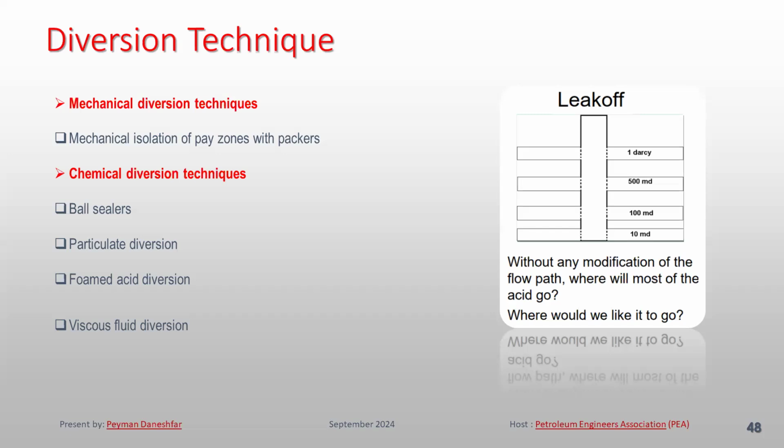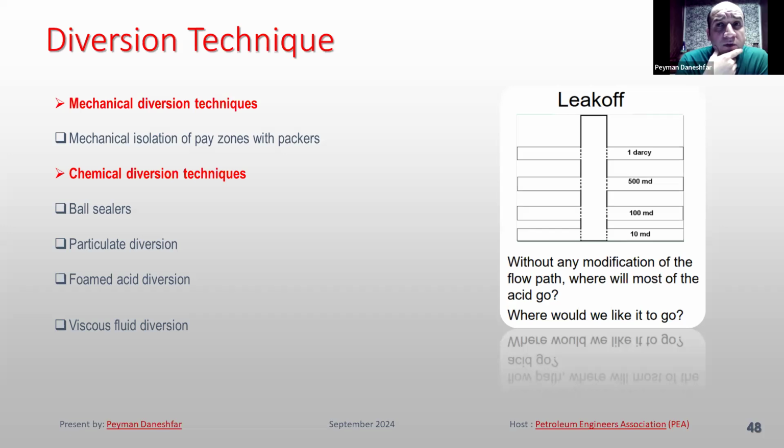Okay, thank you. And for the acid, there are a lot of types you showed us in the presentation, organic and mineral. How can we choose the better type of acid for our well? The acid is normally HCl, and HF is better for sandstone, HCl for carbonate.